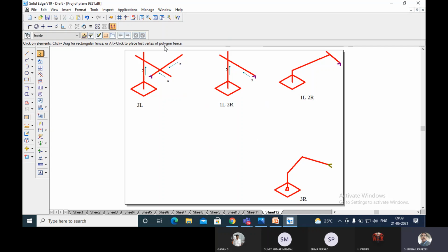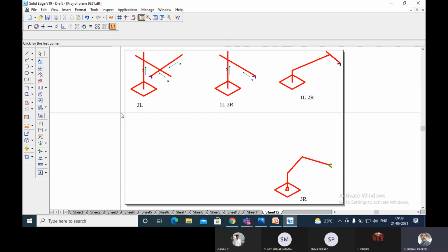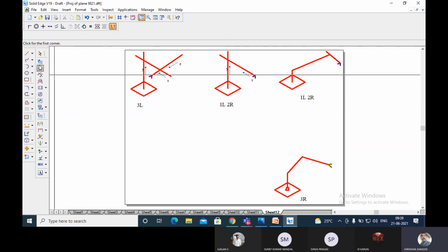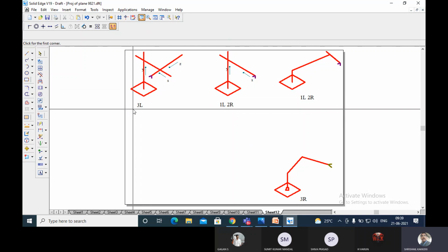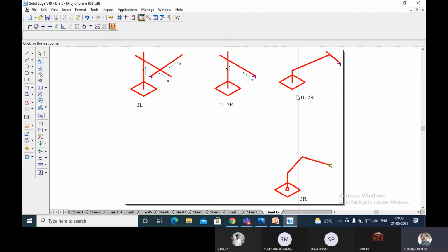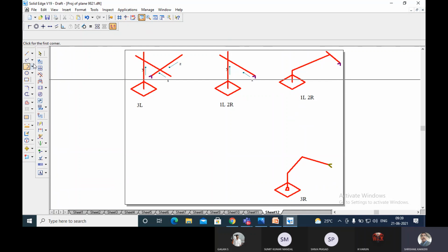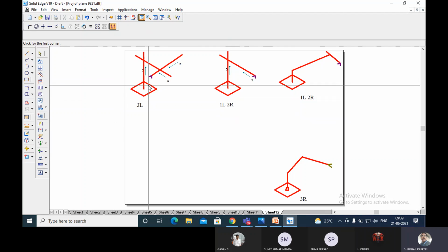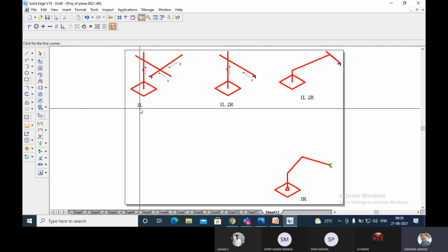Okay, let us discuss the differences between them. The coordinates are Cartesian. This is a Cartesian coordinate robot. The work volume generated will be Cartesian. The work volume generated will be cylindrical. The work volume generated will be spherical. The work volume generated will be complicated. We cannot show it for this. And the mechanical stability will be very good in this, and it can perform pick and place.